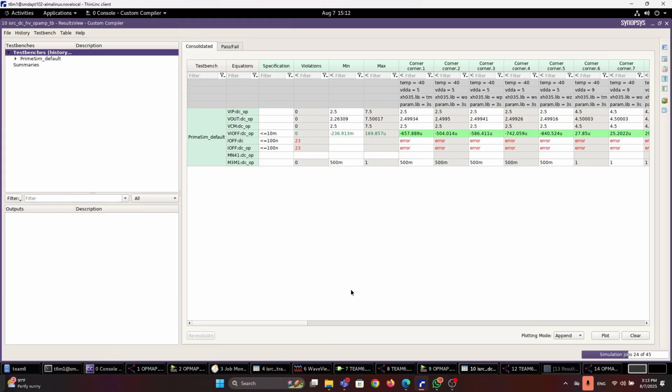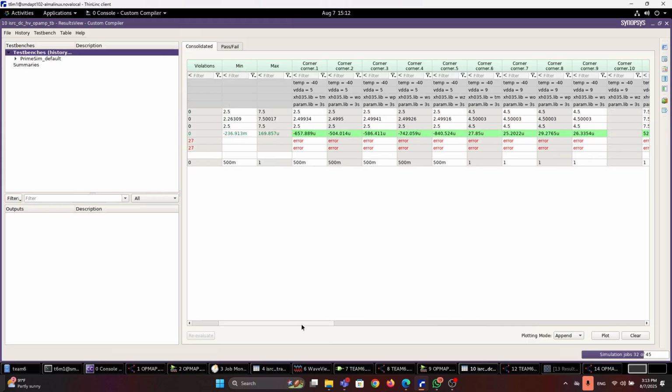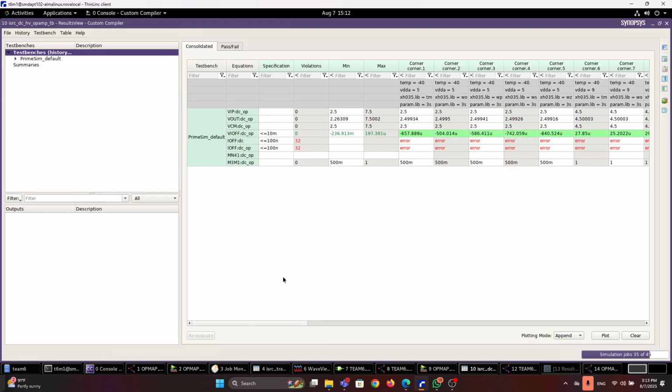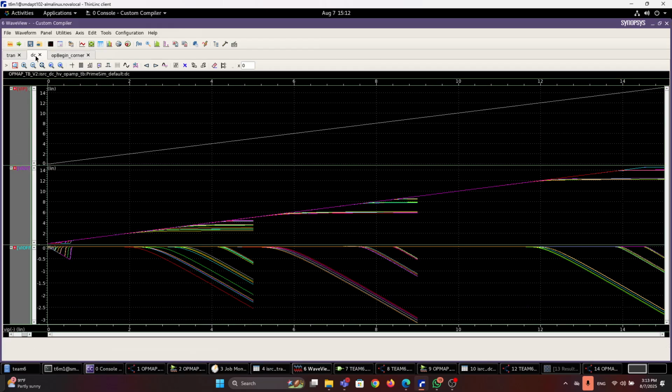So this means that the op-amp was not able to support that much current. That's why the other MOSFET went to cut off. Yeah. The output side, the current. I need to ensure the second stage is able to supply this much current. Oh, so usually the problem lies at the second stage. Yeah.